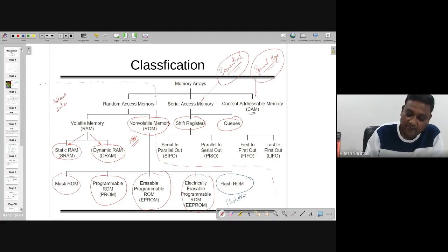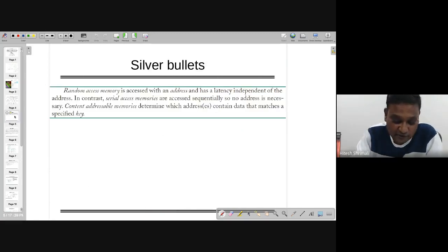This is very popular in design, and in that the circuit has to be changed a bit. The transistors might be CMOS, but they should have floating gates, which can remember the data, and you can erase it electrically only. It's an extension of this EEPROM, but it has been very popular in the last decade, and you can say that flash NVM is actually similar to the volatile memories. It's an extension of that only. Anyway, let's look at what this book is talking about.